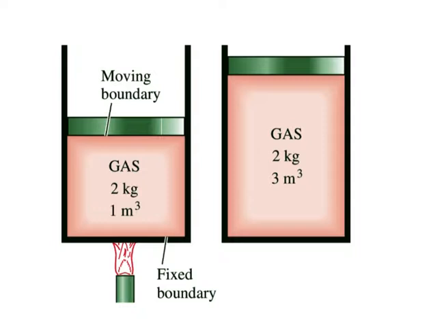An open system, or a control volume as it is often called, is a properly selected region in space. It usually encloses a device that involves mass flow, such as a compressor, turbine or nozzle. Flow through these devices is best studied by selecting the region within the devices as the control volume. Both mass and energy can cross the boundary of a control volume.